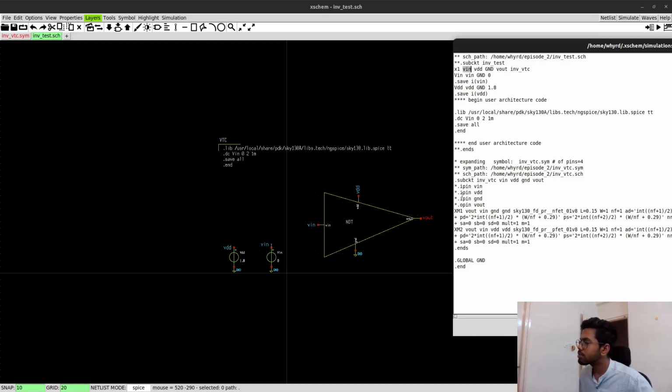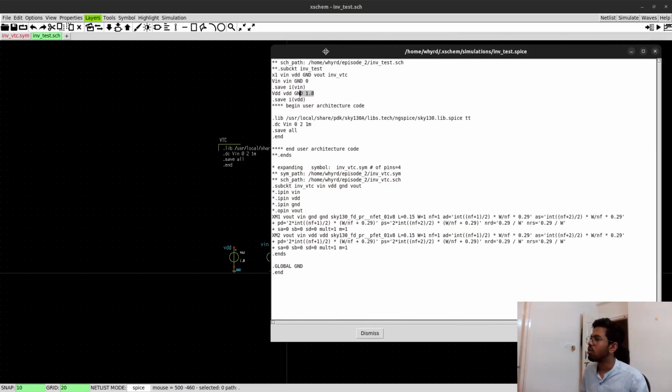And here we are explaining everything: that it has an input pin, and 3 other pins, 1 output pin, and also the device level specification, the MOSFET level, what is the W, and other things which we are fetching from the sky130 PDK. And then these are my defaults. Here I am overwriting V in, because by default, see here V in is 0, and what I have given here is 0, and this is fixed.